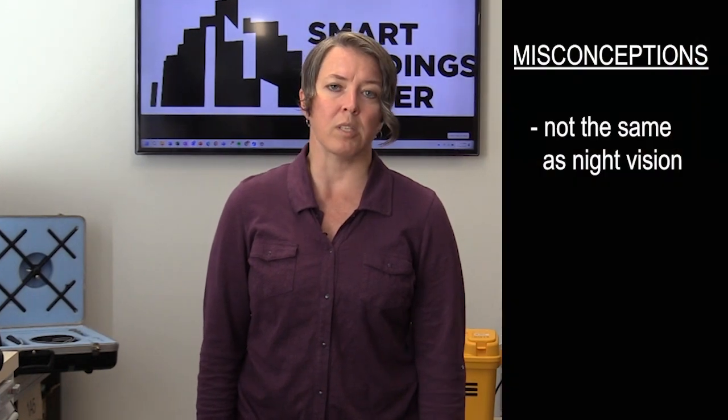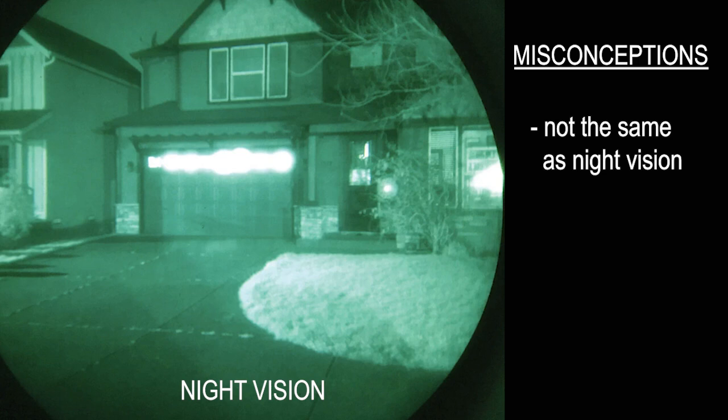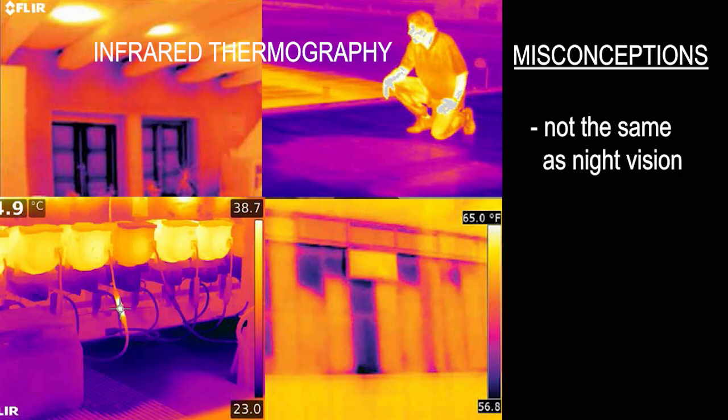Let's talk about some of the misconceptions and what thermography cannot do. For one thing, one misconception is that it's the same as night vision. It's not the same as night vision. Night vision measures wavelengths in the near infrared portion of the spectrum. It amplifies small amounts of light, and so it does require some light. Infrared thermography actually requires no light. Another common misconception is that it can see through opaque surfaces. This isn't true. What it does is it reads the heat signature at or near the surface of an object.